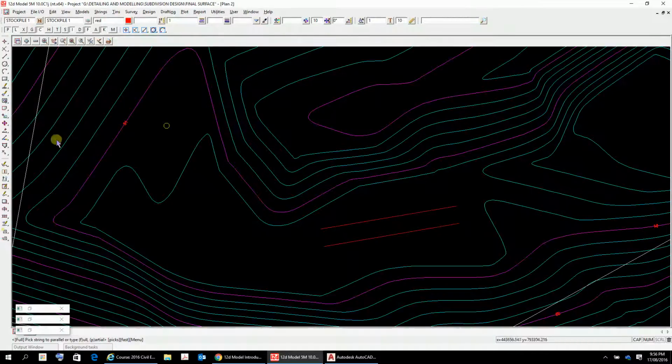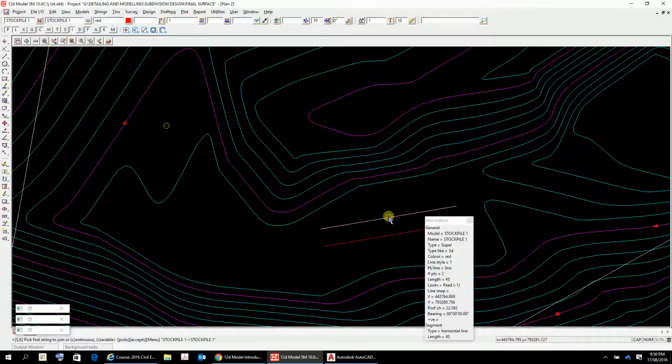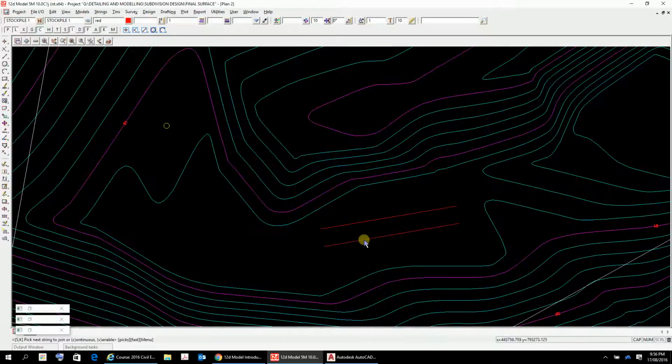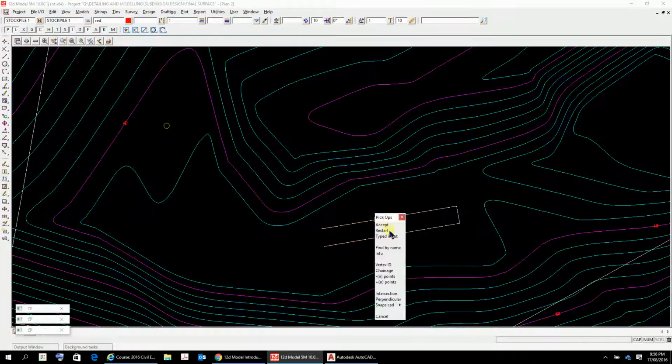Right, so I want to join all those up, and again I can just use this CAD tool here. There's a join command down here somewhere, link join. Again it's click and slide, or click with direction as it's called, accept, click and slide and accept, and that joins up those two. Finally we want to join up the other end, and we use the close function in the CAD here, accept the string, accept. So that closes that string up.